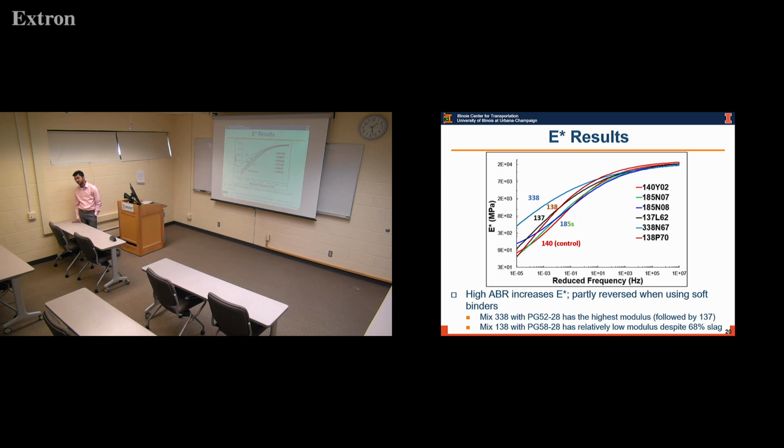It's not exactly a pixel, it's a collection of 20 by 20 pixels in one point, and we have the location of each of them. We plot those locations and select the strains that are higher than 3000 as the locations where we have the fracture process. So you have a preset threshold? Yes, we have code for that.